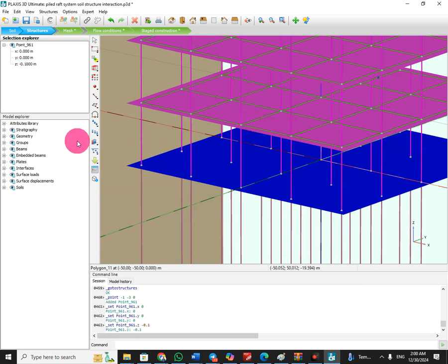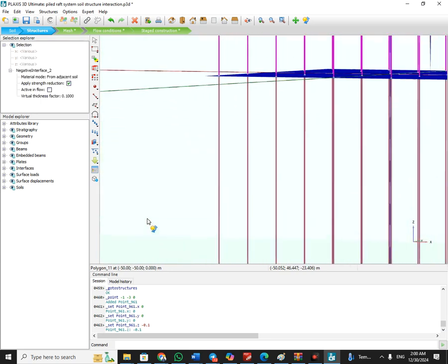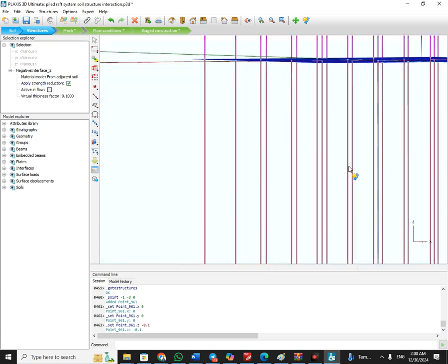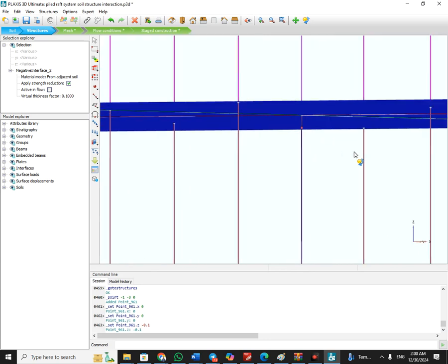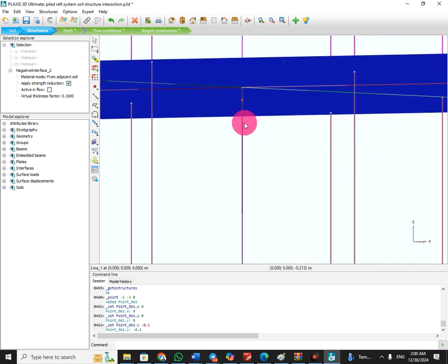Very good. Now keep the control key on your keyboard and the left key on the mouse, and rotate a little. This is the point we need. Look, this point is on the pile, but remember, this pile is not going to be active in our project right now, in the first step. But we cannot always use this point for curves because we have a pile here.